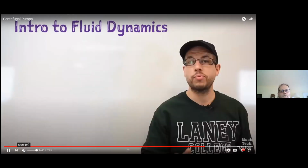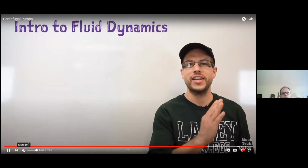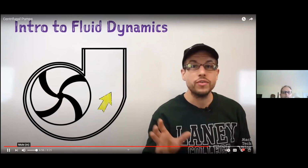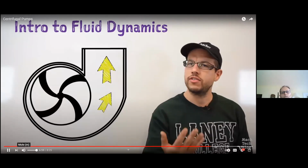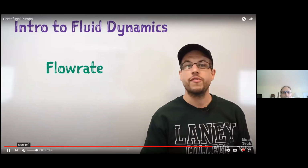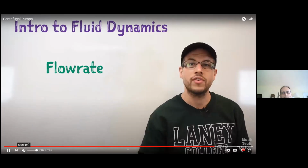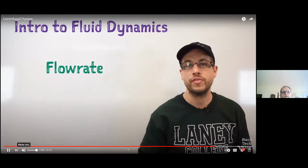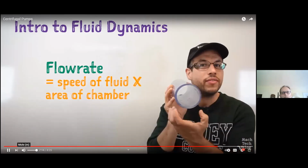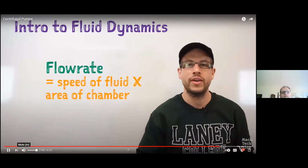To build pressure, the pump has to do some science magic to convert kinetic energy into pressure energy. As fluid travels through the volute chamber, it actually starts to slow down as the area of the volute chamber increases. That's because flow rate, or the amount of fluid which is moved during a given length of time, is dependent on two factors. One is the speed of the fluid, and the other is the size of the chamber through which it's moving, meaning how much of the fluid is moving at that speed.